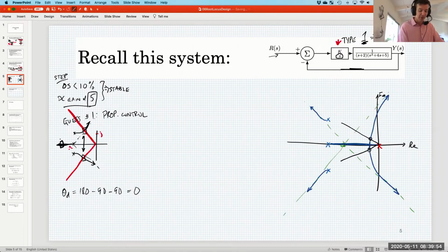But look at what they're trying to dominate against. They're trying to dominate an overdamped mode, which would have the tendency to do what? Bring the overshoot down, because it's overdamped, because it is sluggish in terms of oscillations. And so I don't really think that we would need to dominate this one very much. I think this pole is actually kind of helping us to achieve this under 10% overshoot. So I think the real devil would be in the details about here: how big can we make K to get this DC gain of 5?